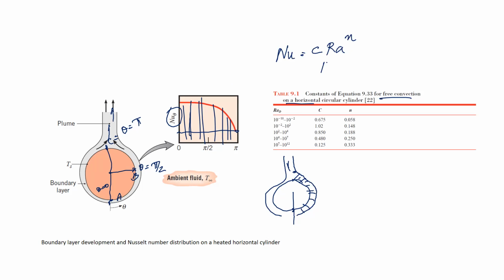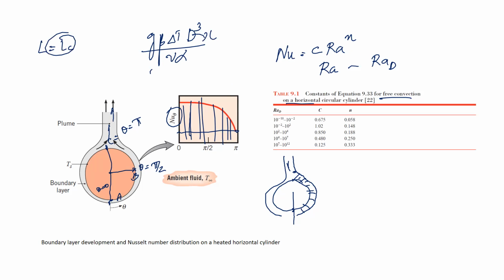So please note that these Rayleigh numbers are defined on diameter. When you write the expression g beta delta T, that will be d cubed by nu alpha. Generally it is L, or it is called the characteristic length Lc. So for different Rayleigh numbers, which depend upon, or are influenced by, our D value for a given T infinity, several relations are expressed.